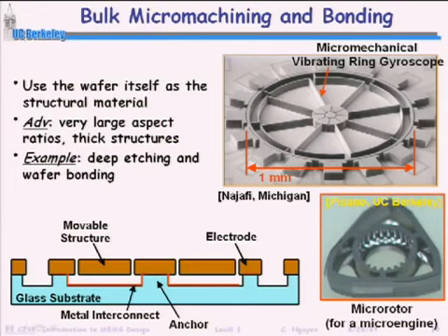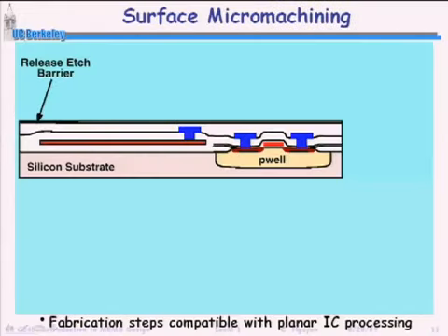So here's the cross-section of an integrated circuit. This is a CMOS transistor there. In order to put MEMS above this, you just continue to do things that you can already do in CMOS, which is put layers down and do etching again and again and again. So go ahead and etch maybe a via down to this jumper that connects the metal from the CMOS transistor to the MEMS device. Put down a layer of polysilicon, dope it and pattern it to make it conductive. This is now your MEMS electrical interconnect.